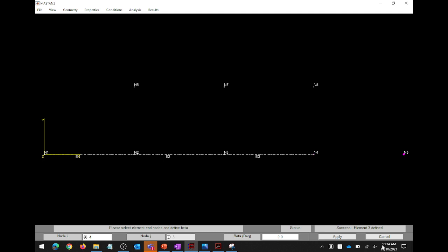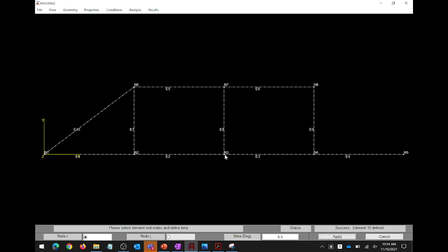Now, one of the things that isn't going to matter on this truss are the stiffness properties and the material properties, because this is a determinate structure. So whatever we define for E or A is not going to change the forces. It's going to change the deflections, but I'm not interested in the deflections. So there's that, and then I think the members went bam, bam, bam, bam. Yep. So apply. So see, I'm sitting here doing this in the middle of class in the space of a few minutes. Your project component should be pretty easy.